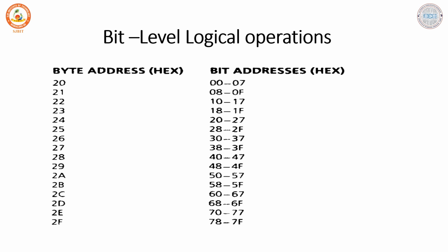Next, we have some bit level logical operations to discuss. When we talk about the bit level logical operations, there are specific memory address locations which are allocated for performing the logical bit operations. The 8051 instruction set allows the modification of even individual bits using these logical instructions.